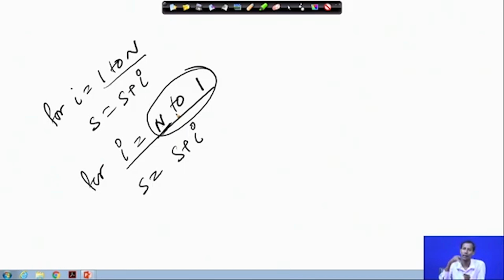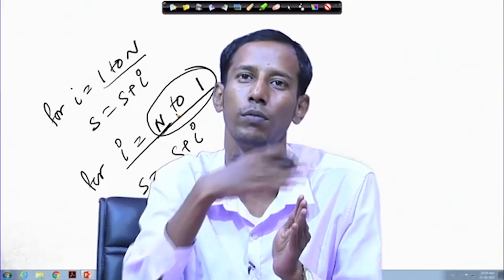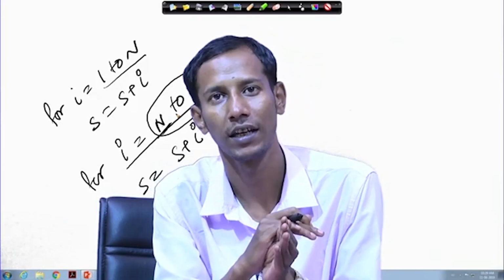So, here in the counter itself, in the earlier logic, from the external bus we know that the user has selected the n value. Then in each clock cycle we check whether the I value, the up counter value, has reached n. Whenever it has reached n, the computation is over and the corresponding output goes to the external bus.